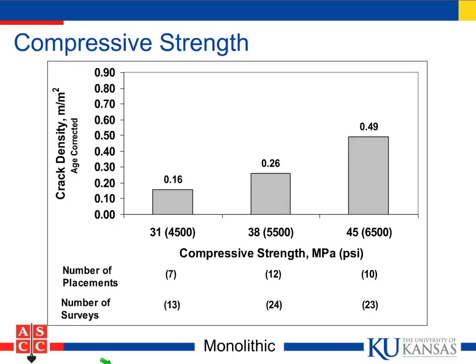Folks are going to hold back water. They want the concrete to get early strength. We can see that high strength is not going to be a friend to you if you have a highly restrained piece of concrete that's going to undergo shrinkage cracking. Now, what's happening here? Well, it turns out that high strength concrete creeps less than low strength concrete.